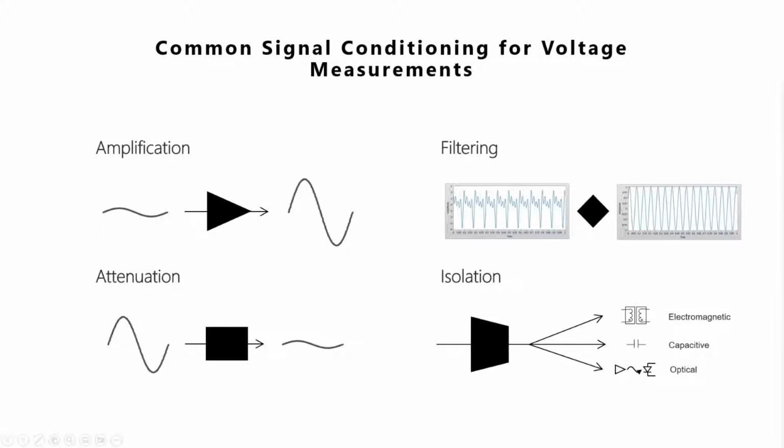Okay. Now, since noise is inevitable in the real world, meaning it's impossible to eliminate noise, especially when you have long cables and a lot of systems stacked together, it's often necessary to filter a signal in order to remove the unwanted noise from the measurement. So a common filter is a low pass filter. You're hearing low pass filter, right? Technically this filters out all signals with a frequency component above a designated cutoff frequency. So it will only pass signals that are below that.